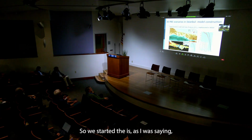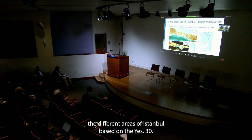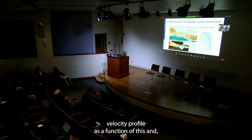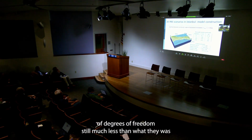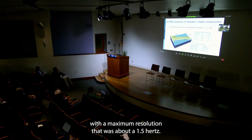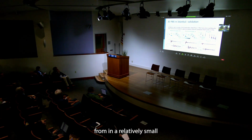So we started from a digital elevation and bathymetry model with a model coming from a microzonation study, from which we classified the different areas of Istanbul based on the VS30, and then we associated to each of these classes a velocity profile as a function of depth. And then the spectral element model was constructed with a huge number of degrees of freedom, still much less than what was mentioned before for exascale computing, with a maximum resolution of about 1.5 Hertz.